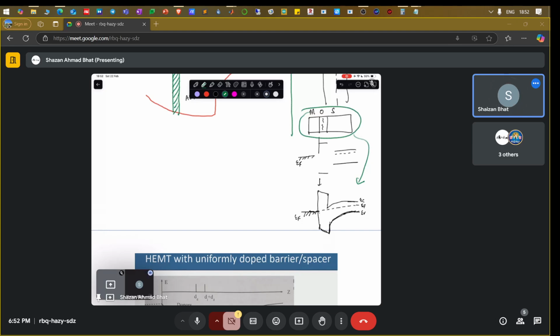And now what is going to happen? Here you might know that if you consider a trap charge inside the oxide, a positive trap charge or a negative trap charge, it modifies the band diagram by bringing the band down at this position and then bringing it up. Here is the positive charge, so the band bends down at this position. It lowers the electrostatic potential energy of the electrons, because a positive charge is definitely going to attract the electrons. The electron would love to live at this place because of the attractive force towards the positive charge.